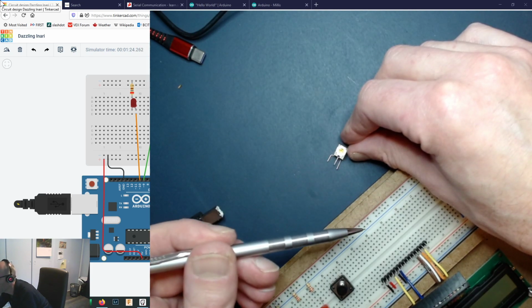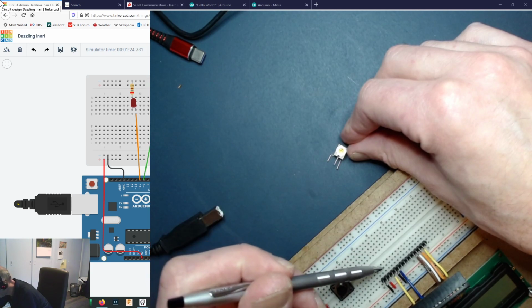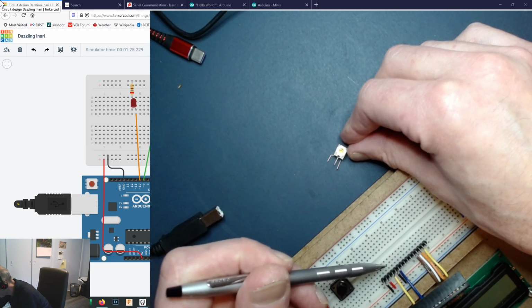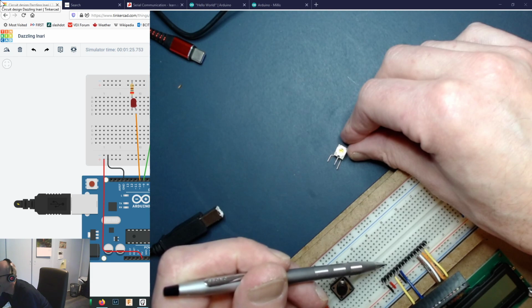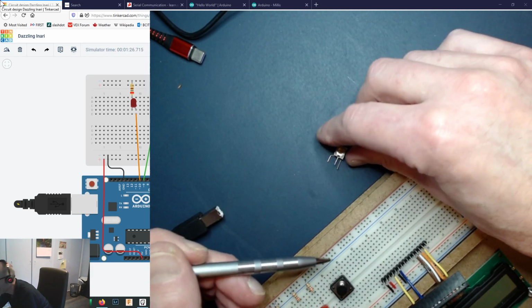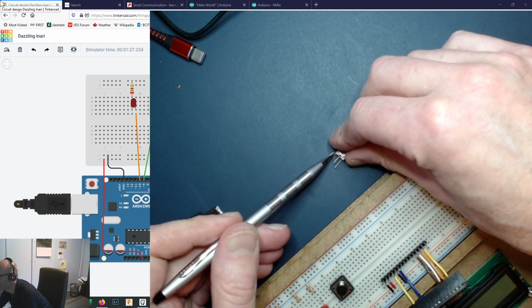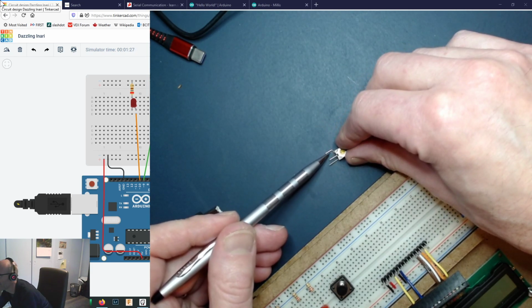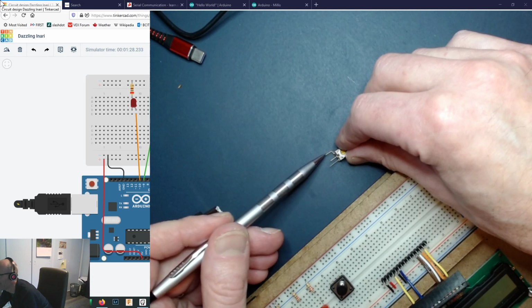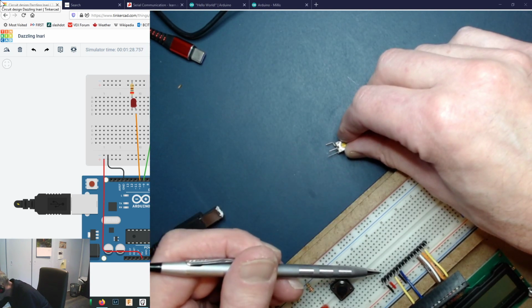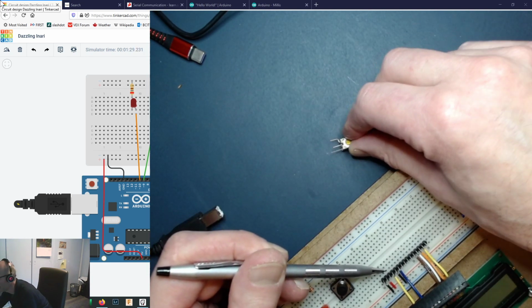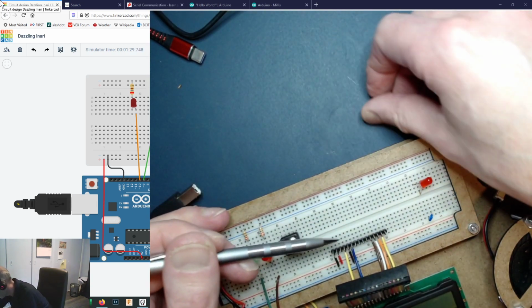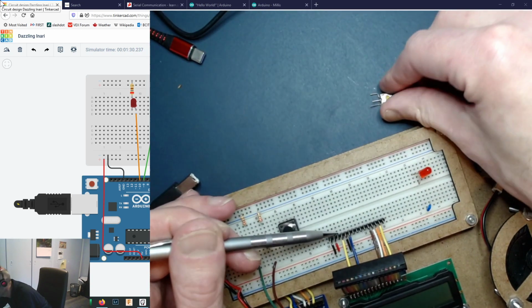Well, 2.5 millimeters. The spacing on here was set long ago at 1/10 of an inch between each of those holes, or 100 thou. And that translates into metric into 2.54 millimeters, or quite commonly referred to as 2.5 millimeters. And the reason we're moving that over one is because I don't want it going into this row right here.